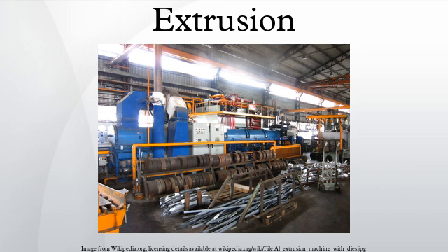Extrusion defects. Surface cracking, when the surface of an extrusion splits. This is often caused by the extrusion temperature, friction, or speed being too high. It can also happen at lower temperatures if the extruded product temporarily sticks to the die.